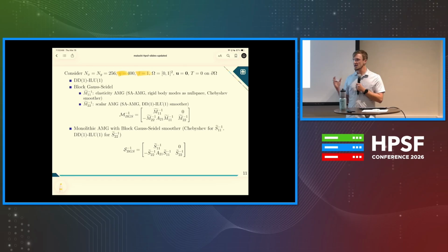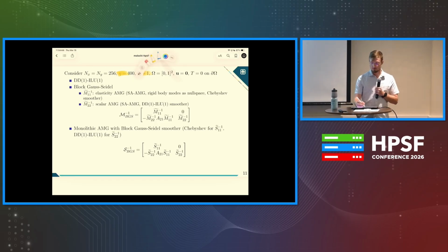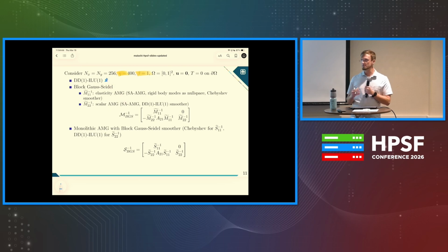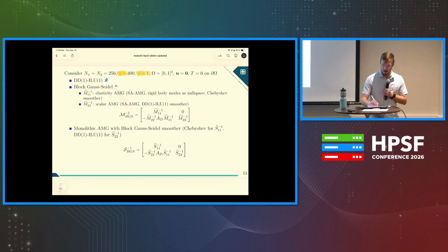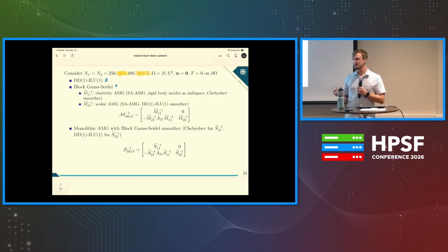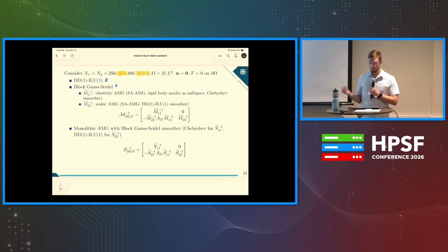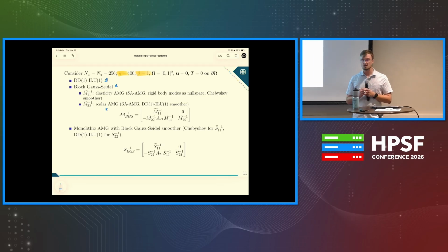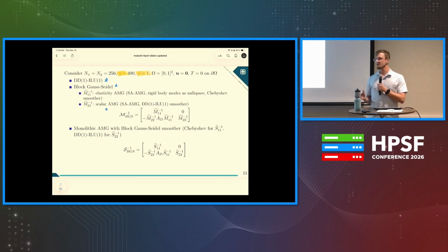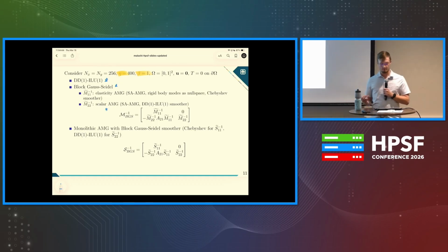We look at that same unit square domain, and let's just pit several different preconditioners against each other. So DDILU with fill and overlap equal to 1. Block Gauss-Seidel, where for the elasticity solve, I use a MueLu setup that is appropriate for elasticity, and for the temperature, I will use scalar AMG, which for the prescribed velocity field I'm using, while it is asymmetric, it's not so asymmetric that I can't use smoothed aggregation.